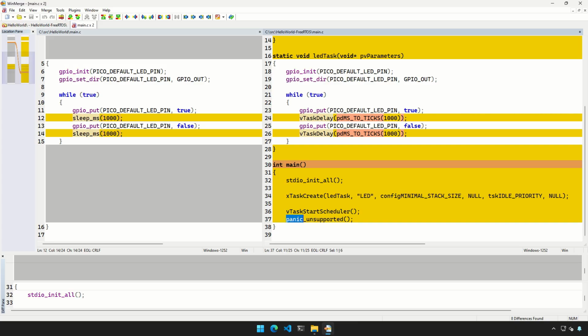It's a kind of fail-safe. Because, as I said, vTaskStartScheduler should never return, so this function has no practical chance to be called. But what it does is just hold the CPU, because it is treated as a non-recoverable error if it enters. So that's the main function.